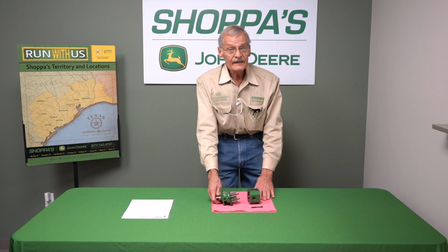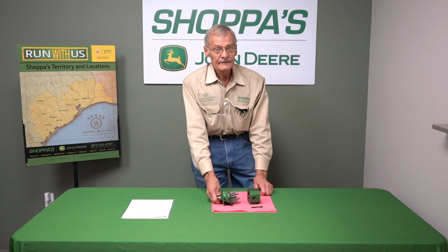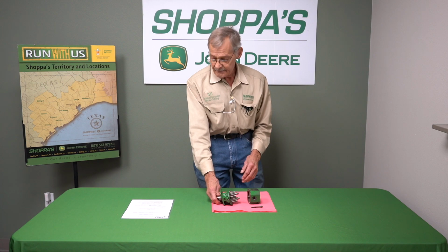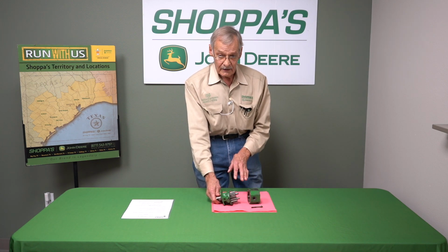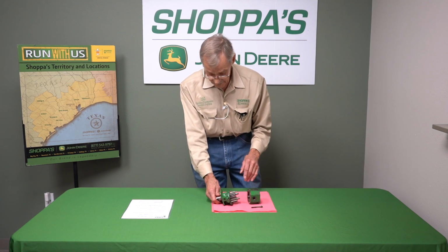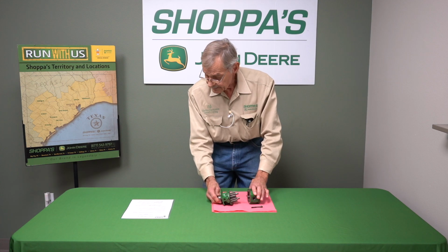The smaller tractors or mini tractors have an open center, meaning that you have a relief valve with which to maintain specific pressure, and not a closed center where you have pressure and volume regulation. But anyway, that is all we have on the gear pump.